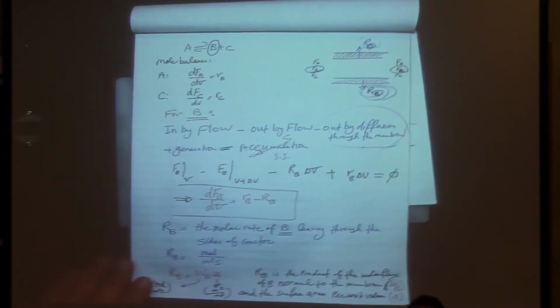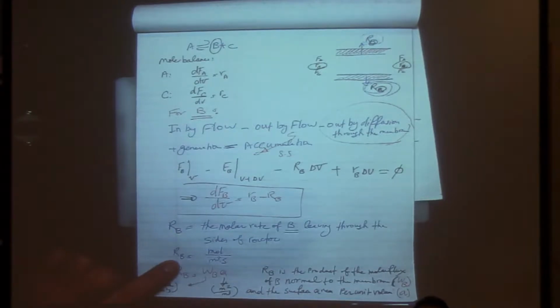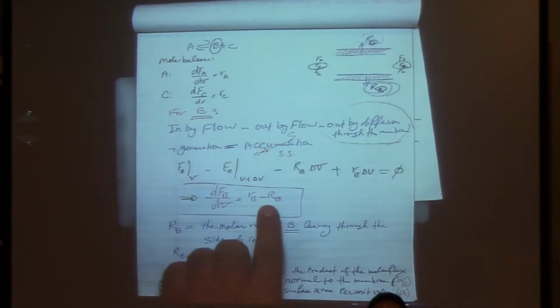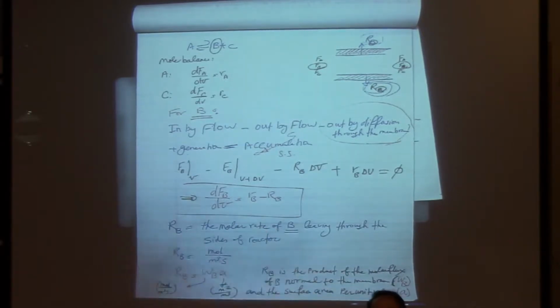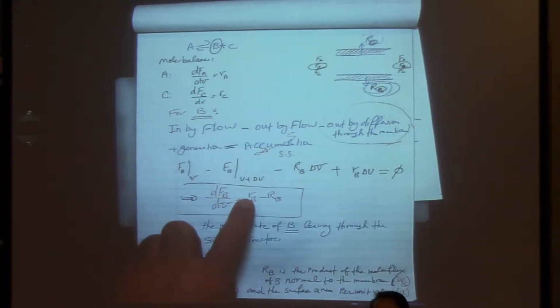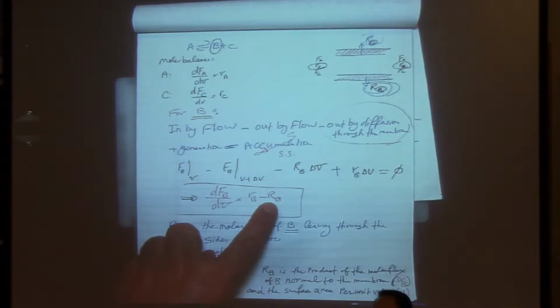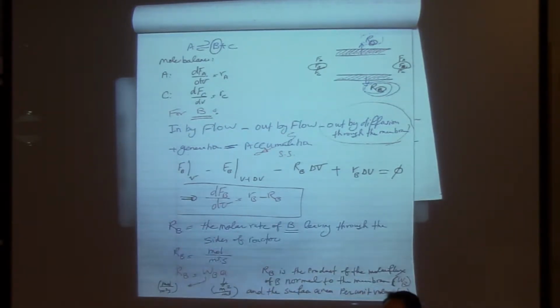So we came to this RV, capital R, which is the same kind of creature as a small r, but with a different meaning. Small r has to do with the reaction, and capital R has to do with the mass transfer coefficient, right? For example, hydrogen goes out of the membrane, so there is no more reaction. There is basically a mass transfer coefficient. That was where we stopped the other day.